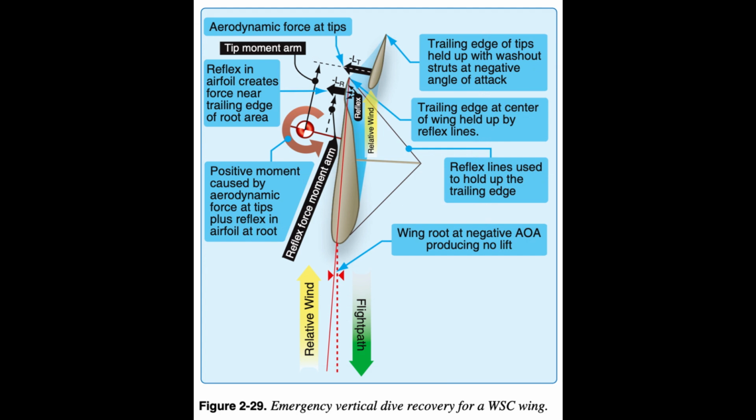Phase 2, if the rotational movement is enough to produce a vertical dive, as illustrated in Figure 2.29, the aerodynamic dive recovery might raise the nose to an attitude to recover from the dive and resume normal flight condition. Phase 3, the rotational momentum is enough to bring the nose significantly past vertical, the nose is tucked under vertical, but could still recover to a vertical dive and eventually resume a normal flight condition.